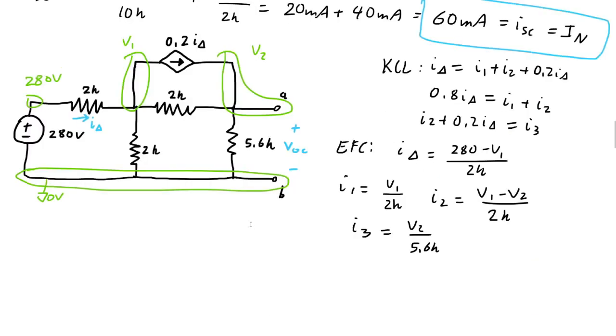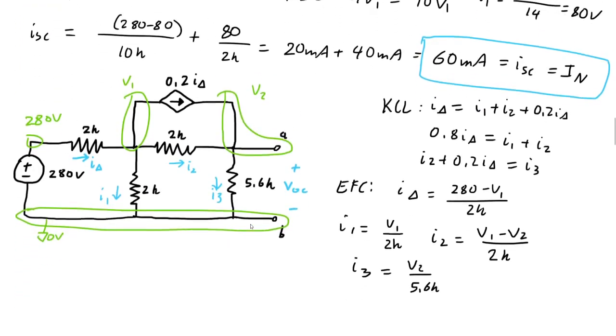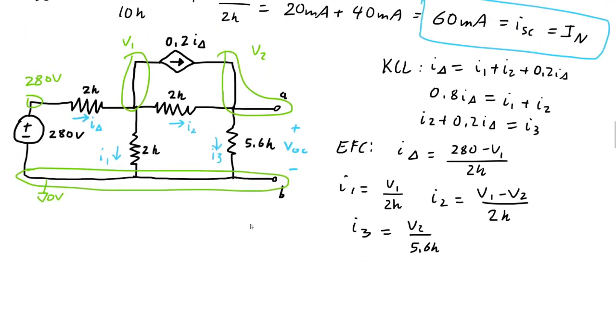Okay, so now we're going to go ahead and solve for the V open circuit, the V Thevenin, so we can find R Norton. Anyway, I copied the equations down from the last one. Let me make sure that I use the same names for the current. I think I did. Yeah, I2, I3. Since we're not going to have that short anymore, V2 is going to equal V open circuit, because we have B over here, and then the A. So we need to find what V2 is, and then we'll know everything else we need for this to work out.